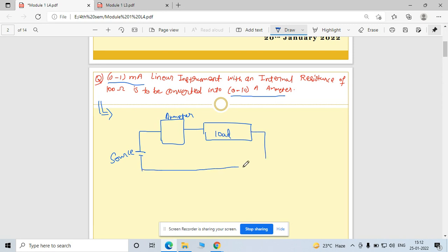Now you want to measure the current flowing through this load, consumed by this load. For that you need to connect the ammeter in series with it. As you know, the internal resistance of an ideal ammeter is 0. Similarly, the internal resistance of an ideal current source is infinite. That's why a current source is connected in parallel with any load, and the ammeter is connected in series.